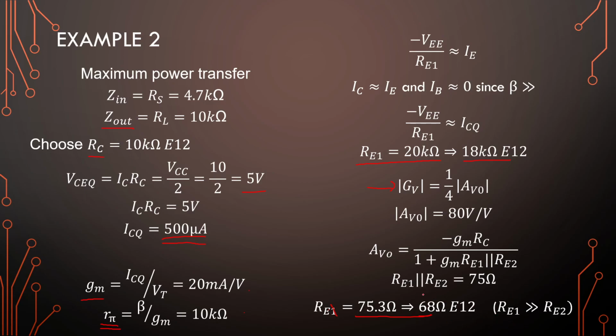And the choice of this component, we can go a bit down because that means that our gain will increase slightly. If we go too large, our gain would decrease a lot. Okay, so it's typically better to choose this one a bit smaller to compensate for losses in your circuit. Okay, and it will usually work out kind of nice if you choose this one downwards.